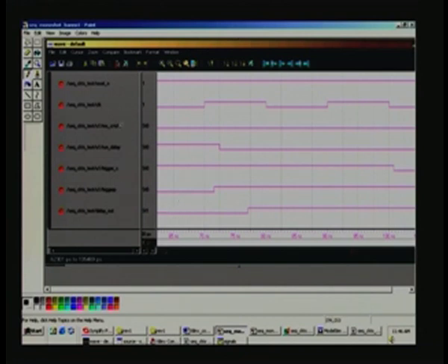The counter is CNTD here, and as I mentioned earlier, some of the counters are totally separated out. If this is a 16-bit counter, you will get all the 16 signals listed, you may have to manually group them, which will be very tedious. That is the reason why I could not show you a counter here, and that is not a handicap, because what we are really interested in is the final output itself.